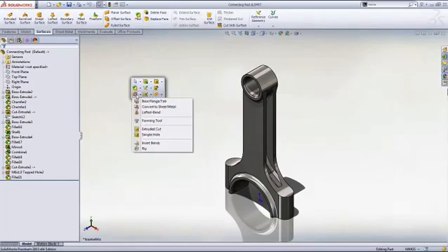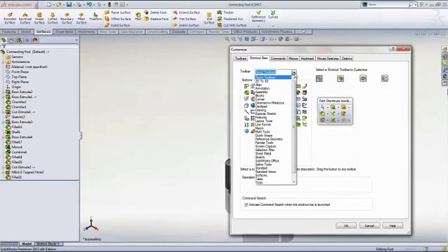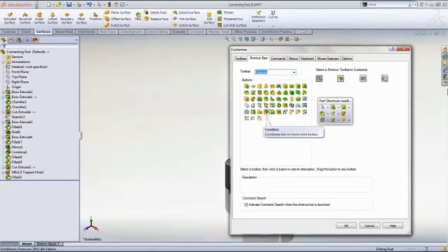With the shortcut bar up, just right mouse click and choose Customize. Now, I'm using SolidWorks 2013 here, and this is a little easier in this version, but previous releases work fairly similar. Here, in this drop-down, you'll see that I have access to all the tools in the software. For instance, maybe I want to add some of these pattern tools from the features list.